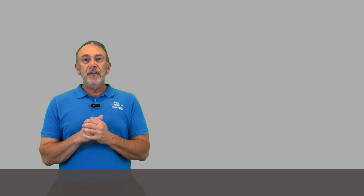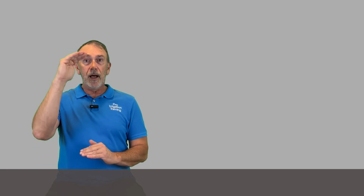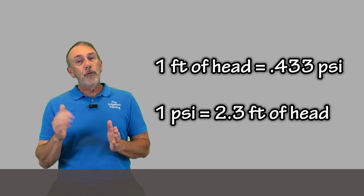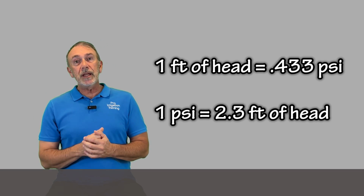So let's talk about our other measurement, and that's feet of head. You're not going to see this a lot until you start getting into pumps and calculating what size of pump you need for the system and so forth. So a feet of head is the measurement of a 1 foot column of water, right? Which is 0.433 psi. So 1 foot of head equals 0.433 psi. 1 psi equals 2.3 feet of head. Now, that's not going to mean a whole lot to you until you get into pumps and so forth, and really PSI is the only thing that we're going to be dealing with.